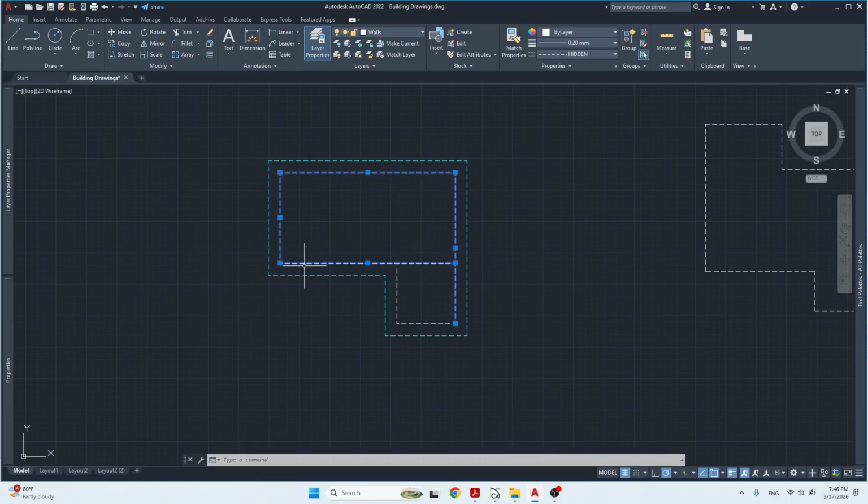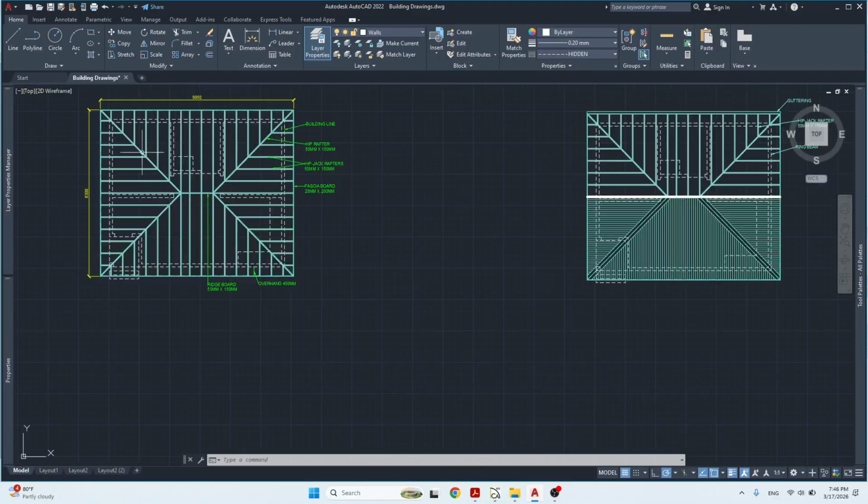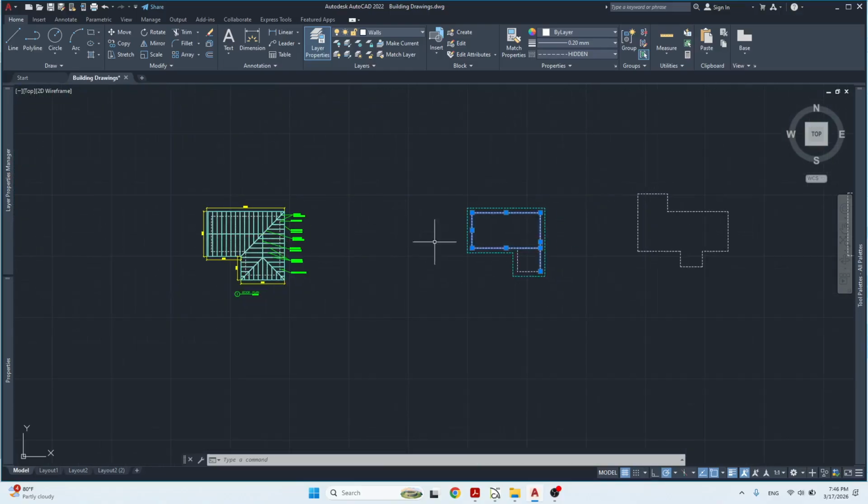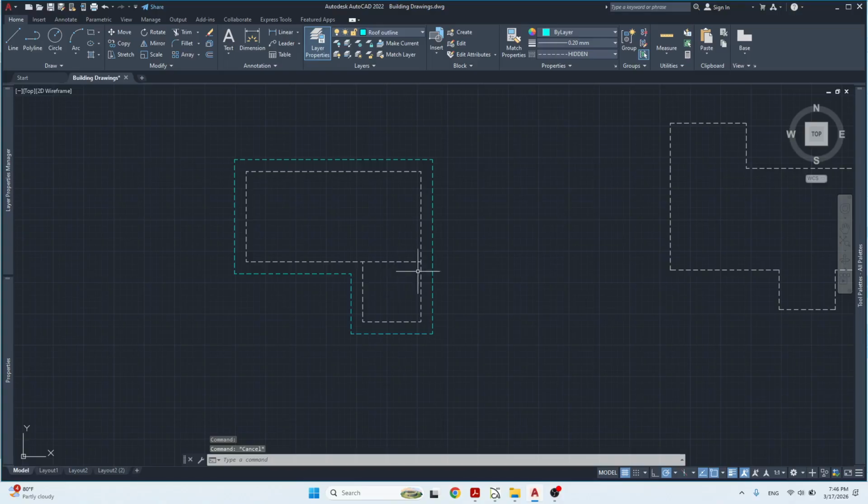And as we know, it should be fairly easy, just like here, to create a roof with the ridge in the middle and the hip rafters from each corner of the rectangle. Very simple. So we're going to treat this as its own roof right here in the middle. If this is my wall, this is my overhang, this is my wall here, this is my overhang. So I need to extend my overhang all the way out. Now I have my overhang here, here, here, and here. That corresponds with each side of my wall.